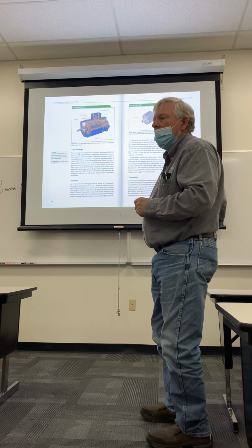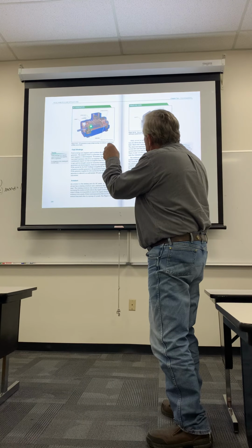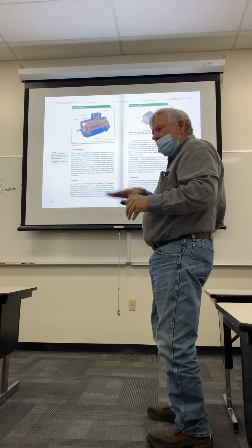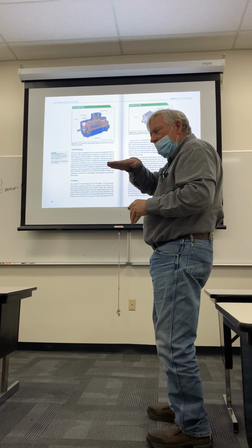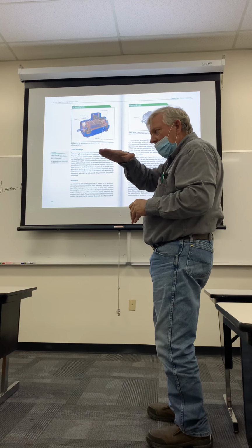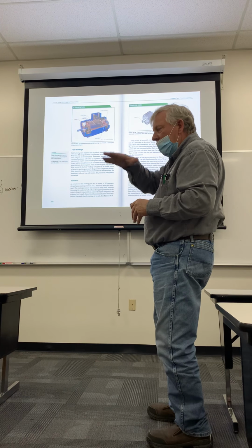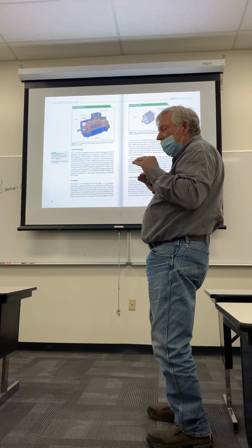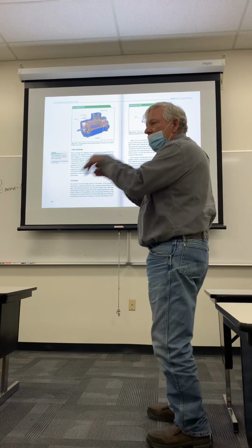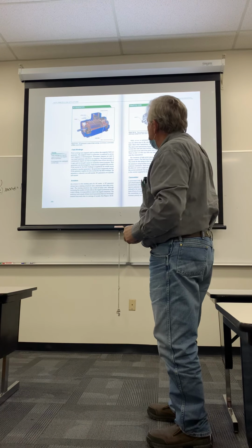Notice you can see a slight little angle to them, the way those are put in there. A lot of them look very straight, but they have a slight angle, and that's so those magnetic lines push that armature away from it. It pushes it in the direction that you want it to spin.